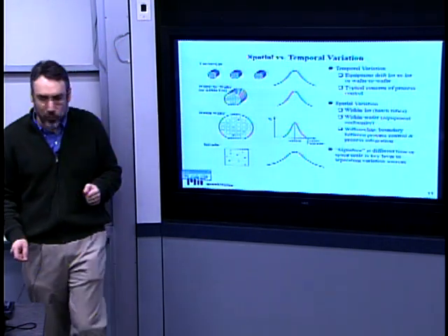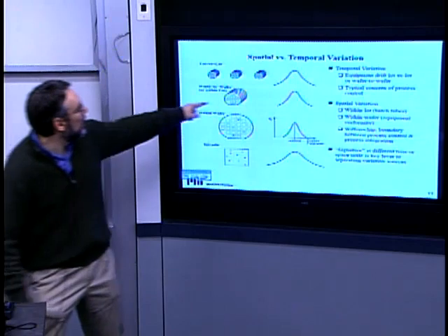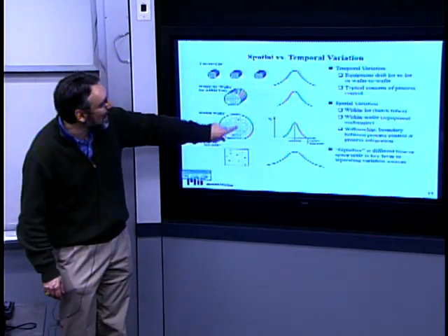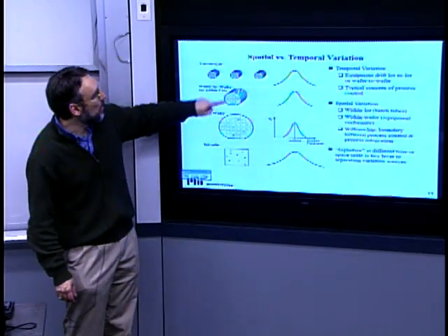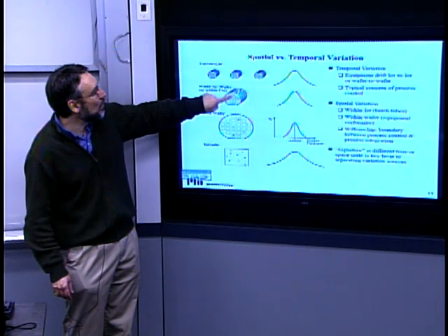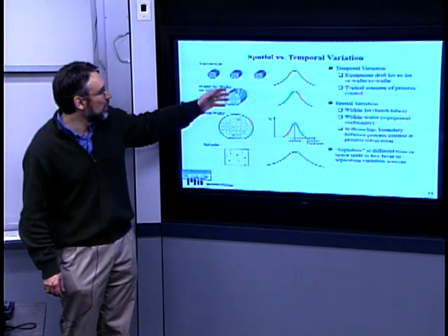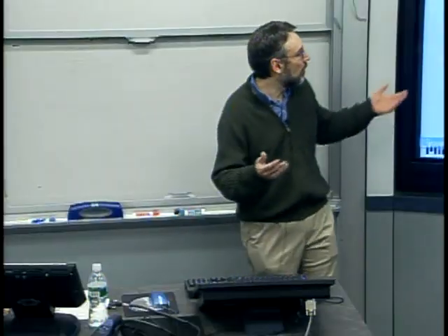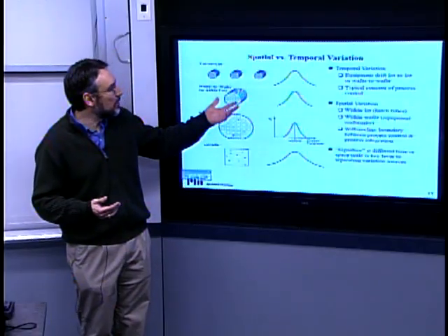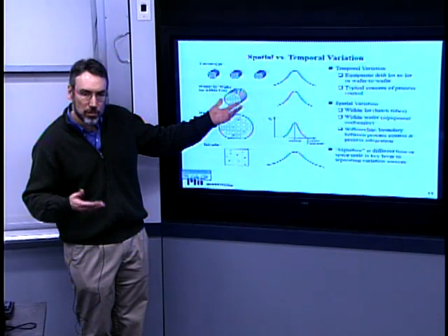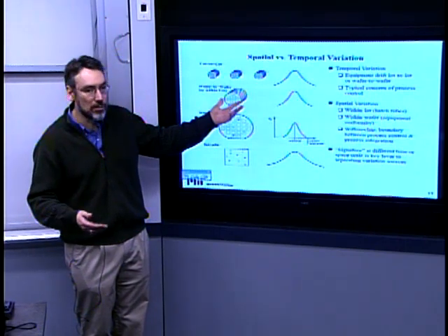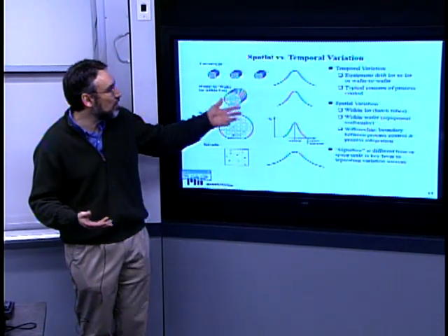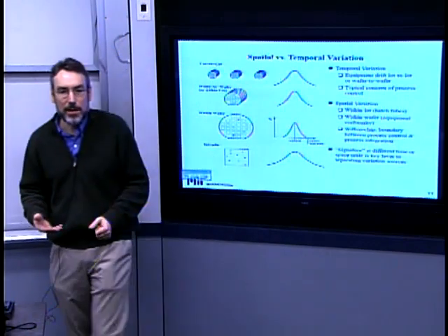Now we also can have wafer-to-wafer variations. Again, if I were to either calculate the average over one wafer or maybe just sample exactly the same location on every wafer and stack that up across 20, 24 wafers or large numbers of wafers that might be in one lot, processed even relatively close in time to each other, there's also going to be a deviation.